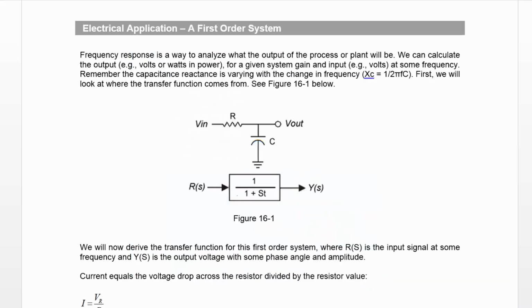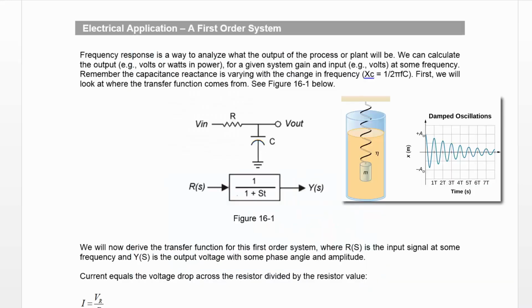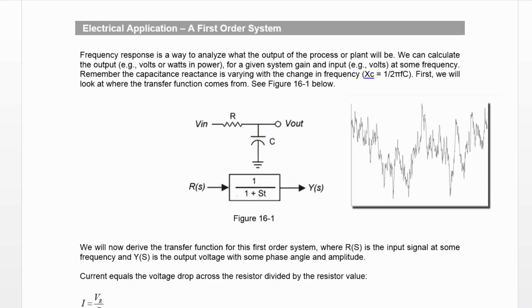You can get other noise too. Splashing in a tank on a level. As the water comes in and hits the top, it splashes. So the level kind of oscillates a little bit. And it puts this little ripple of noise in your output signal of your process variable measurement. Okay, we may want to get rid of those noises. And this has to do with a frequency response.